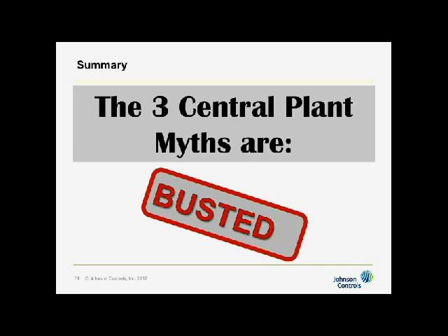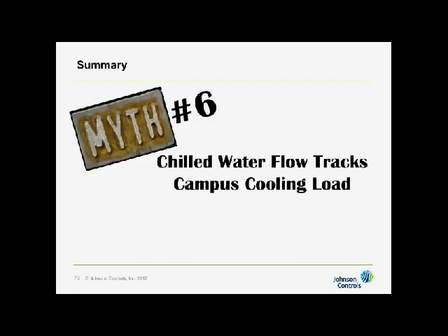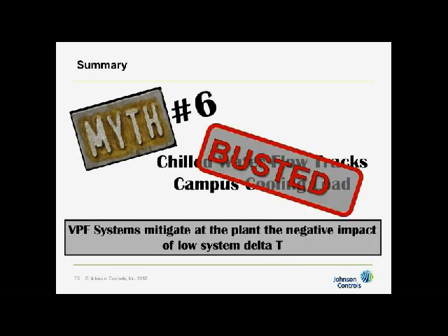And now we're just going to summarize everything that we talked about today. We talked about 3 central plant myths. They are busted. Number 6, the chilled water flow tracks campus cooling load. That's busted. VPF systems mitigate the negative impact of low system delta T.